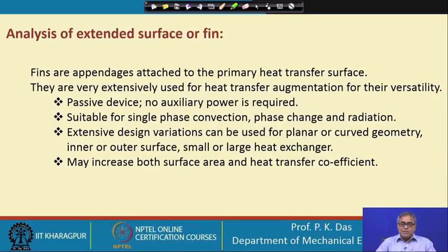A fin is a conductive convective surface. Initially the primary surface we had had heat transfer by convection. Now, we are providing fins on it, still it will have heat transfer by convection, but we are giving some extra area to the primary surface. The extra area will not be as effective as the primary surface area, but in any case this extra area will enhance the rate of heat transfer. So, this is the whole game.